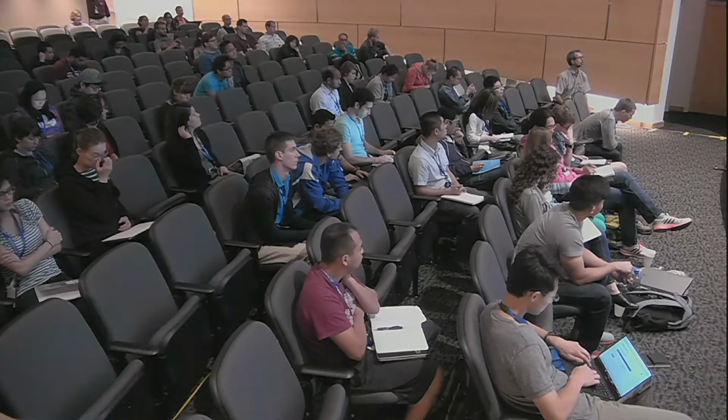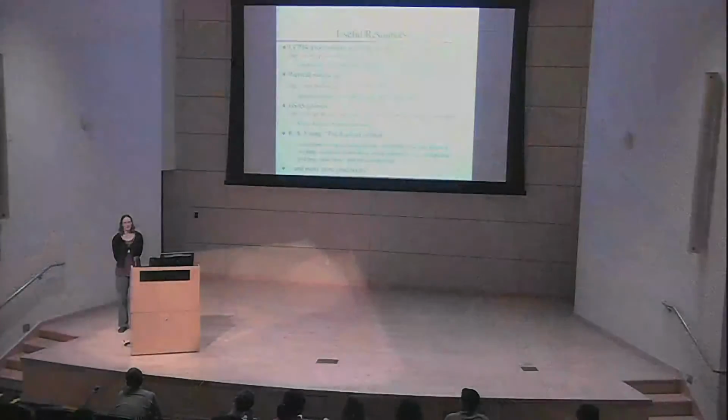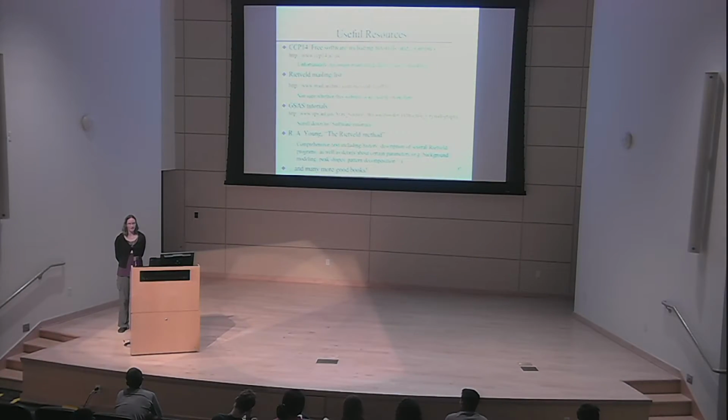So how much do I account for the shape of the peak, not just the basic width that comes from the instrument when I look at the broadening? So what we usually do is we run a standard over a large angular range. And then we extract the full width at half max. So the asymmetry will affect that a little bit. But if we went further down to the peak tails, the asymmetry would have a way bigger contribution to our peaks.